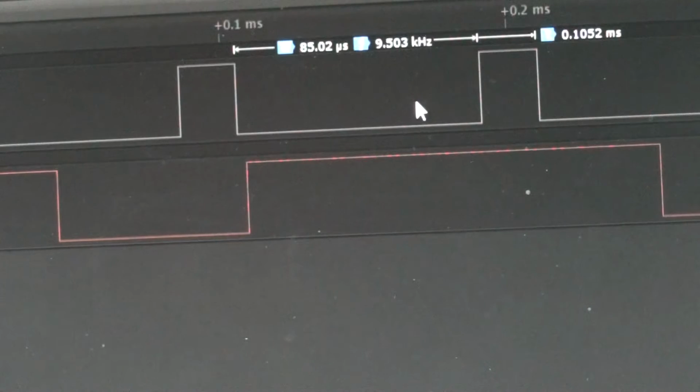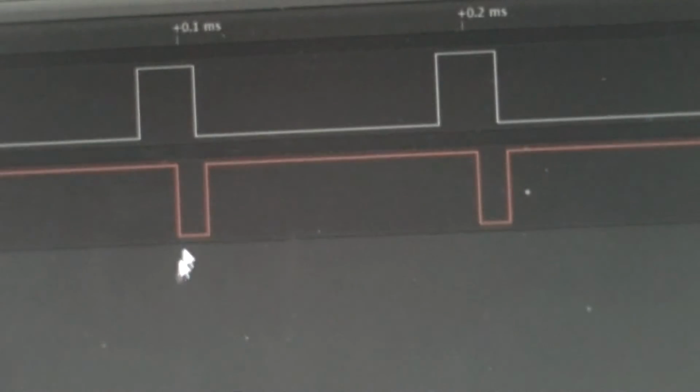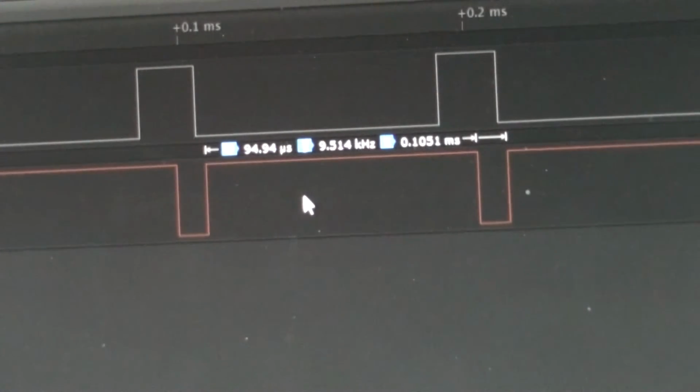that it wouldn't be practical to have a 10 millisecond pulse at all, because if your incoming frequency is 10 kilohertz, it's going to be way longer than the period of the frequency that you're actually applying. So 0 to 100, or less than 100, is going to be the maximum you can do. If I wind the potentiometer back down to a much lower value, then reset, you can see now that it is practical to have a higher frequency coming in. Anyway, that's something that you can experiment with.